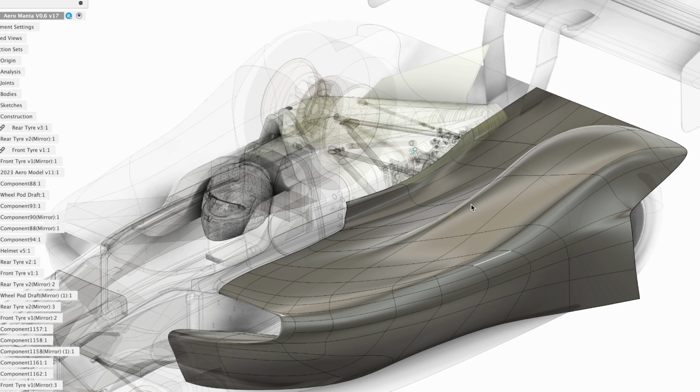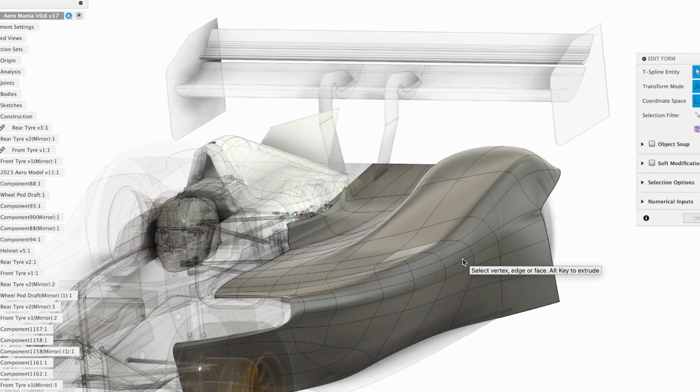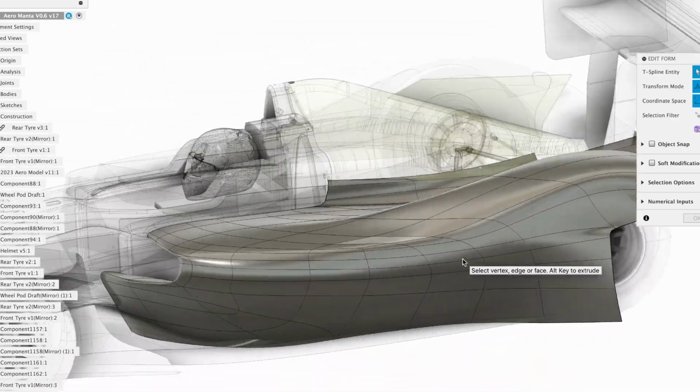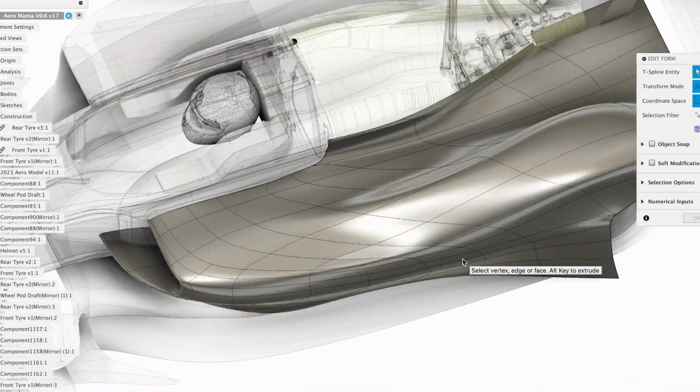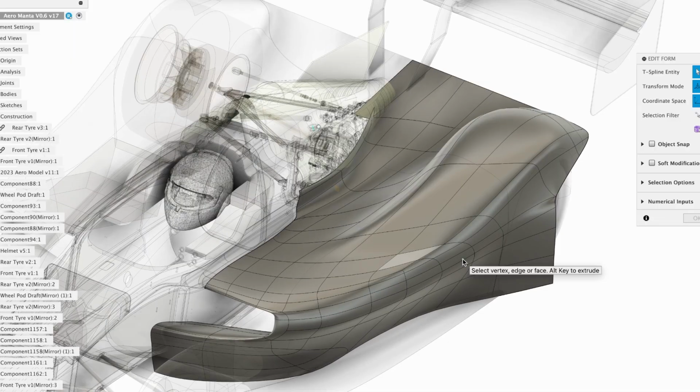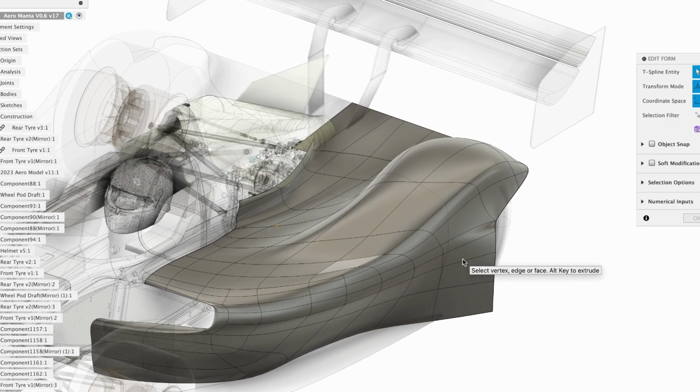However, part of Airshaper's code essentially makes anything you chuck in there into, be it a low volume, but a volume itself, which will work with the CFD code. So this is great for me because I can combine this with Fusion's T-spline modeling. And what you get is almost like a blanket of splines that you can drag around and manipulate to change the shape of the bodywork.